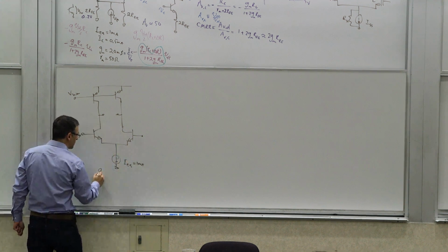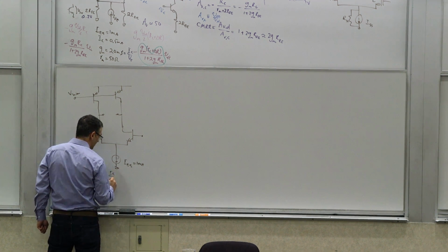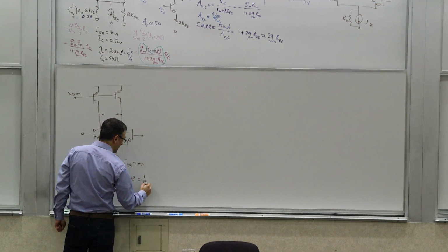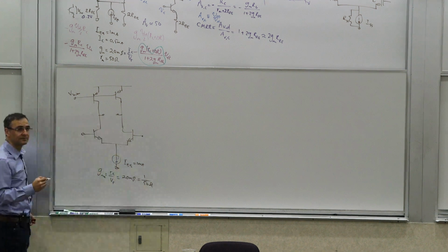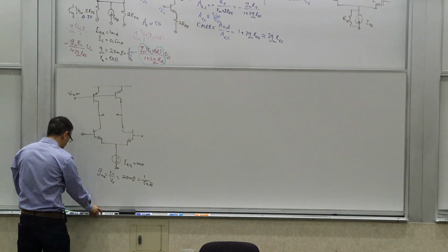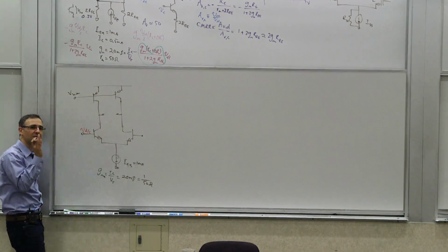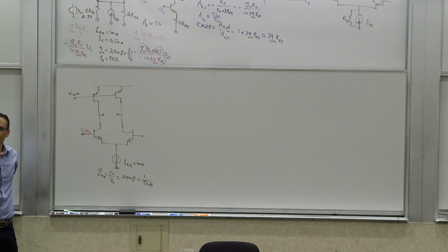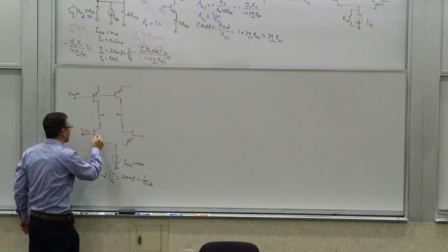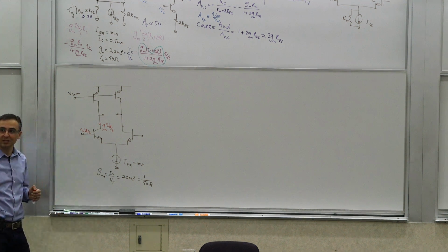And so therefore, for each one of the transistors, GM, GMN, would be IC over VT, half a milliamp each, so that's 20 millisiemens. It's 1 over 50 ohms for RM. Okay, so that's the same. Now the question is, what is the output resistance? Now, of course, the gain here is determined. So if you think about it, what I'm doing when I'm writing these things is really drawing the small signal model superimposed on the large signal model, right? So we are doing our small signal model in our heads, and we want to get used to doing that. So this is going to be GM VID over 2. So that's the current that's being pulled out of that node. That's a fluctuation. That's the small signal current.